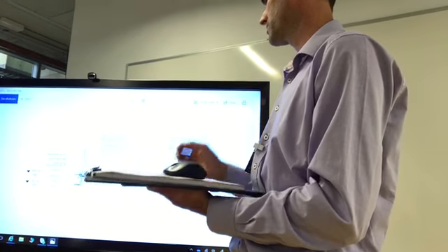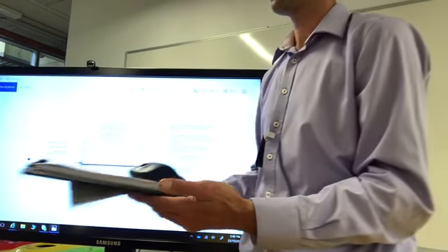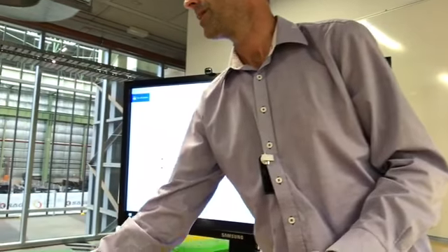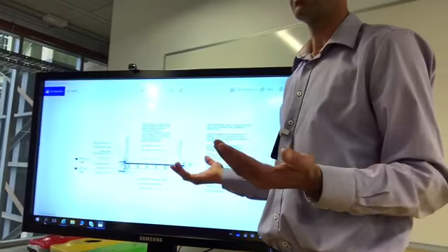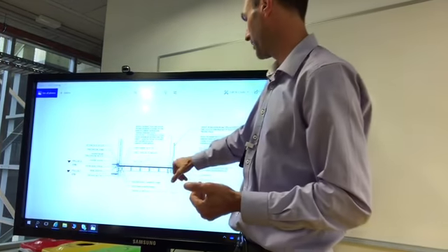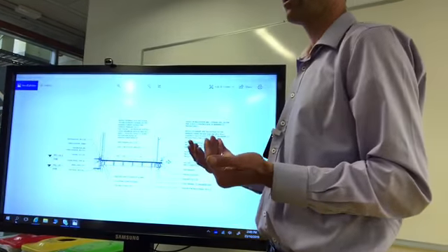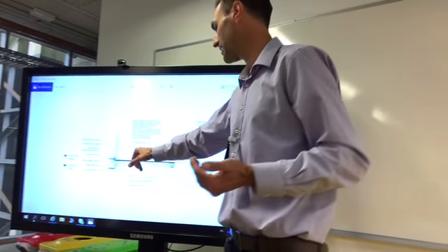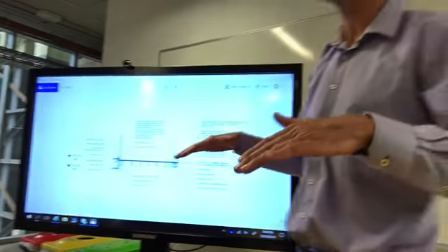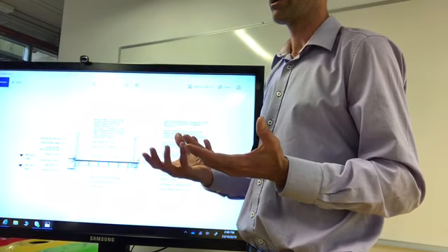If we were going to detail this up in terms of not allowing our water to exit off the end of our balcony, then we would have a hob here, same like you do in a shower, or you'd have some sort of detail for actually retaining water on the balcony, and then you'd have the slope to a drain as well.